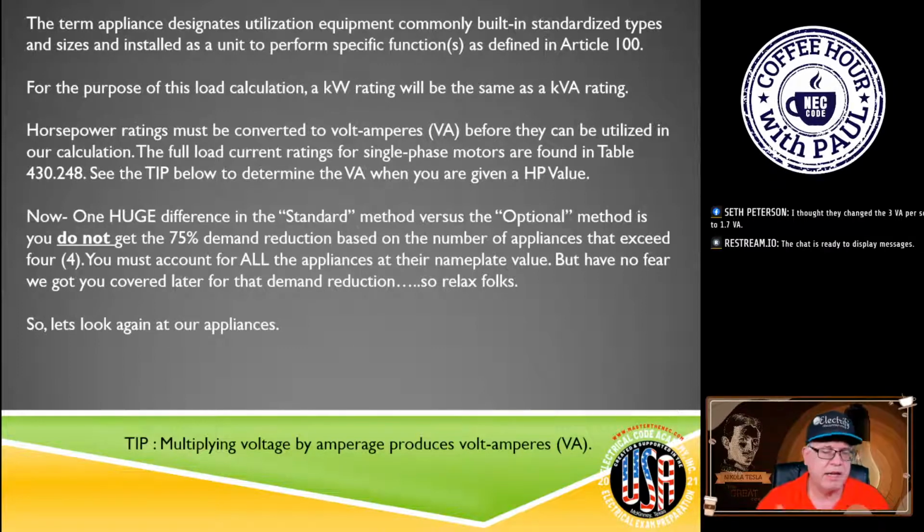Again, reminding you for the purpose of these load calculations, kW is the same as kVA. Don't get that confused. Now, when you're looking at the different motors, in the real world they'll have a horsepower rating on it. That distinguishes it as a motor, especially if it's important for us, for example, when we're doing a standard calculation for the largest motor application. Now, in our case, the only time we're going to need that when we're doing the neutral is if our largest motor has neutral loads, right? Because we're sizing the ungrounded hot conductors right now. That's what we're doing at this moment.